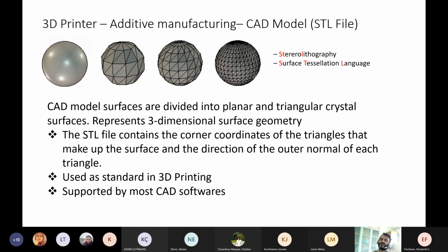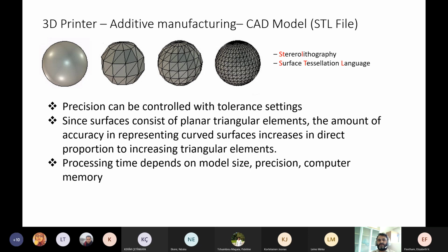It's the easiest method to define 3D shapes with complex internal structures as a series of layers from a 3D CAD model. So it's easy to derive slice data from an STL file. It's important to use enough triangles in the parts in STL files. For example, a cube model requires only 12 triangles, 2 triangles in each face. So this provides maximum resolution.